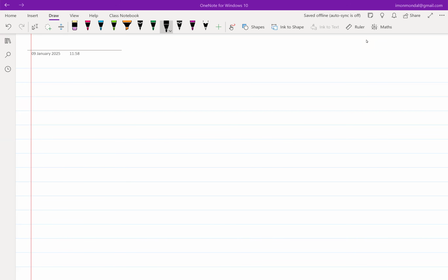So then we saw that in order to do that, we need some nonlinear operation or maybe some time variant operation. The time variance part we haven't talked about, but at least we know that if you use nonlinearity, then some sort of frequency translation can be done. And that is something that we can use to move the desired frequency of operation to a higher frequency, right? So that is where we ended.